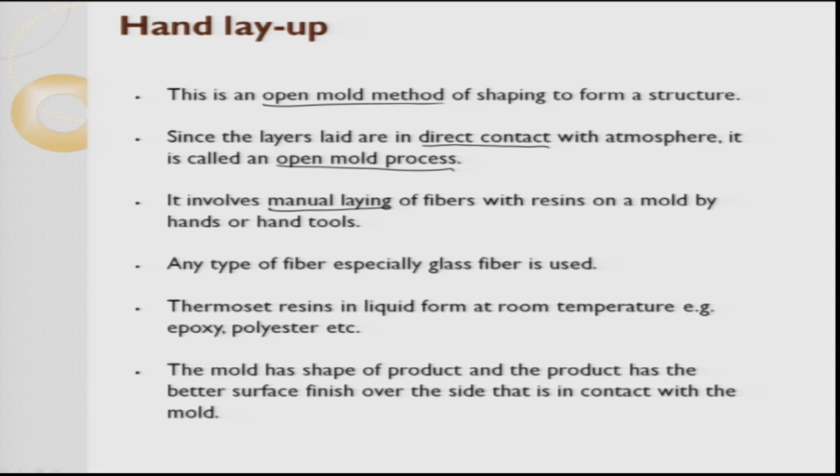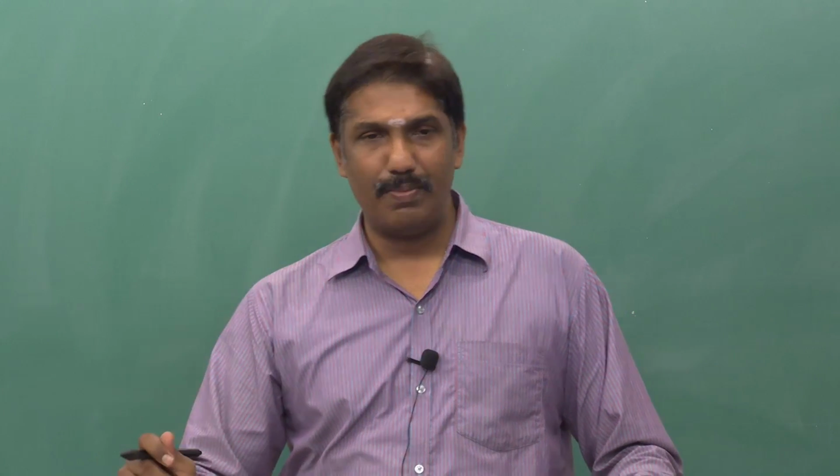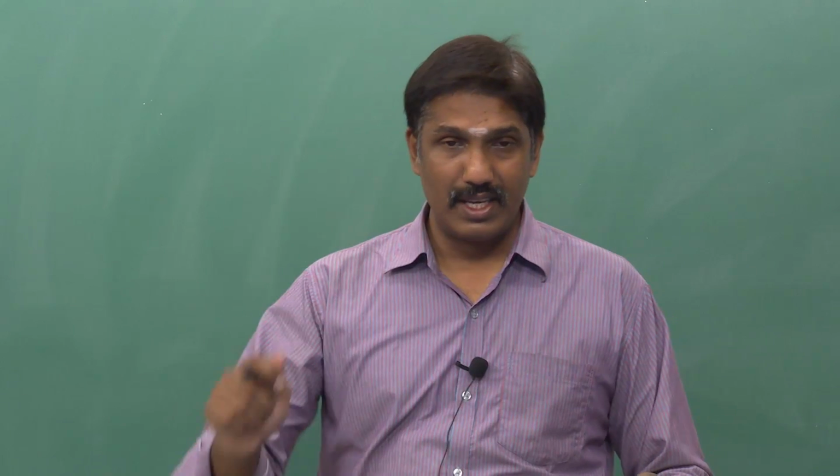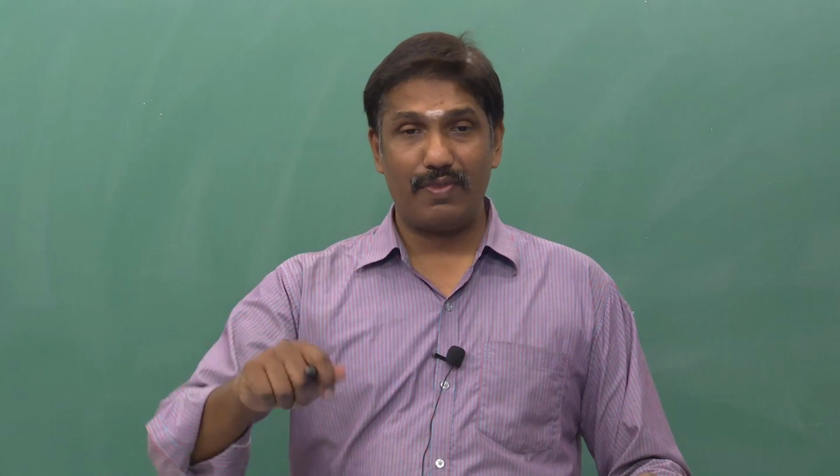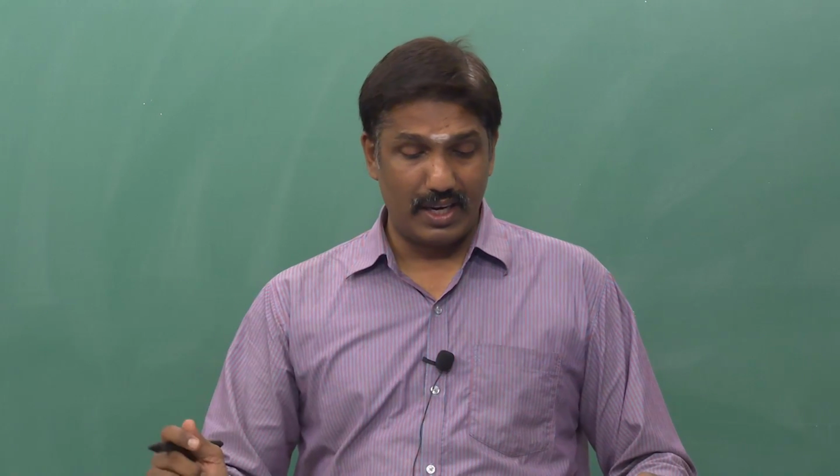Moment the fibers are manually laid, so what? The production rate is low. Okay. And the second thing is, the advantage is it gives me a lot of flexibility while building a component. For example, I can try to put an integral part inside, and if I make a mistake, I have a possibility of tweaking it. And since I always use my hand, the most flexible and controllable gripper ever made is our hand and wrist. So, I have a lot of flexibility to move my hand and try to get the required form.